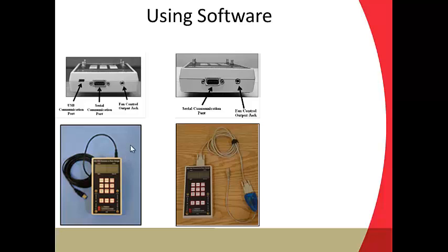Another option is using the serial communication port. These are old school communication, but there are definitely advantages to them. We've run 3,000 feet of cable and not had any problem with signal loss. So that's one nice thing about serial communication, you're pretty much unlimited how long a cable you can use and get good solid communication. You can use regular communication cable.